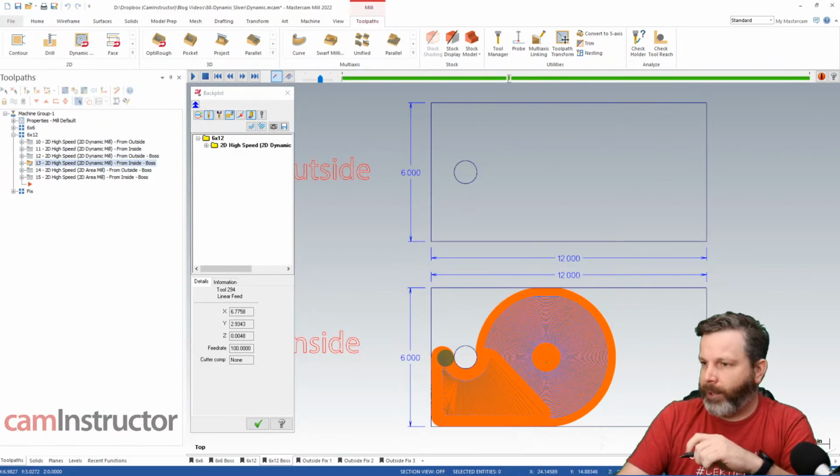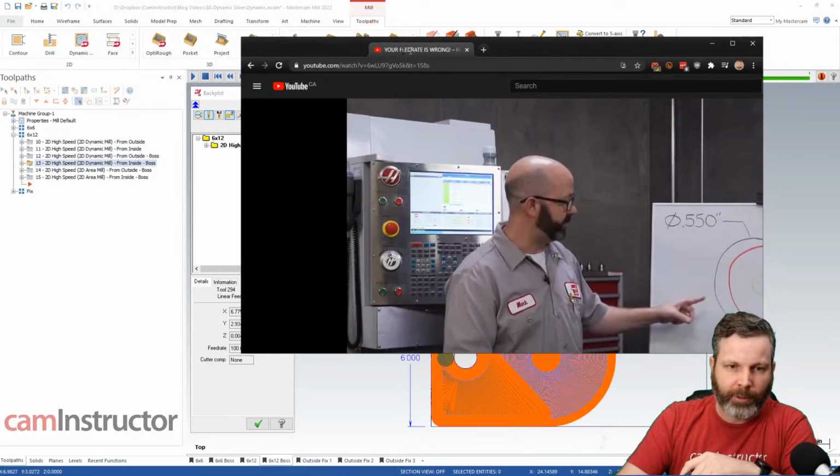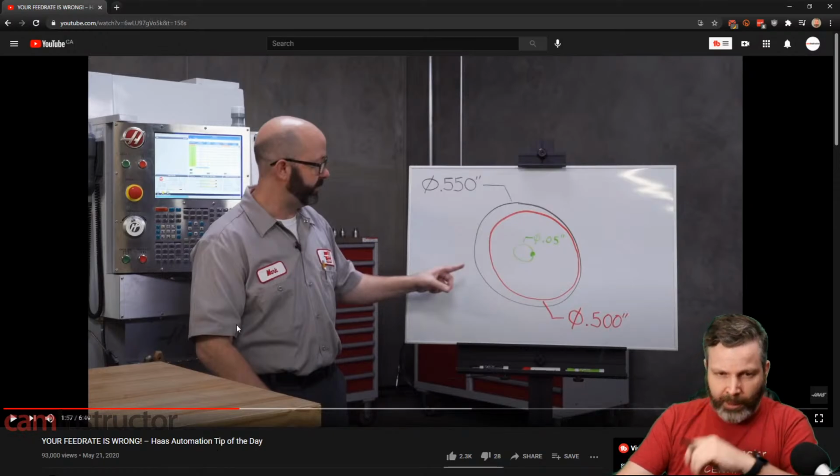Let me bring this page over here for a second. I did a video about this a while back, and Haas also did a video about this a while back. So let me just bring this over. Those of you might have seen this. If not, please go watch this video. It's a really good video. Mr. Terryberry here is talking about cutting a hole that's .550 in diameter with a tool that's very close to that feature's size. So he's got a .550 hole, cutting it with a 1/2 inch end mill.